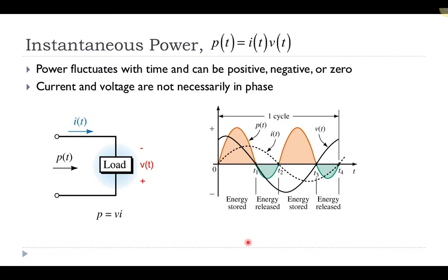In this presentation, we discuss power as it relates to alternating current circuits, and we're going to define power in terms of the different components that we've looked at: resistance, capacitance, and inductance. So in general, we could talk about the power in a circuit, or the instantaneous power, and if we wanted to calculate the power, we would multiply the current times the voltage.